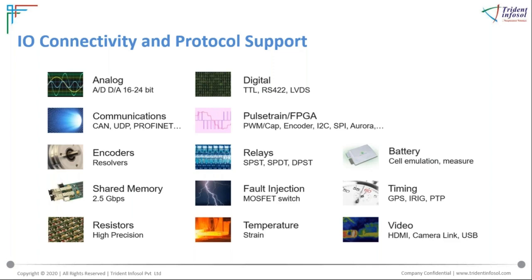For the relays, we offer different types of switches based on the number of channels that would be required. And also we have cards for fault insertion, where you can deliberately connect a signal to ground or short two signals and see how the system behaves. So you can simulate different types of fault scenarios in real time.